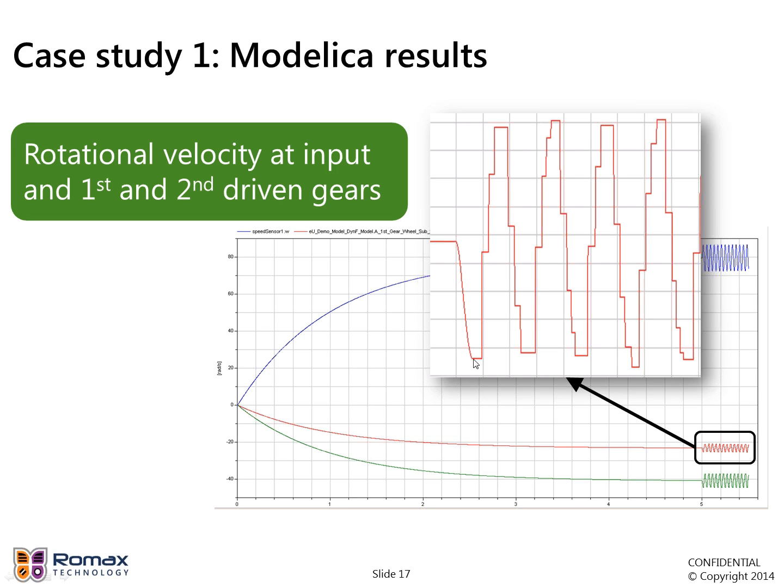At various points here, here, here and here, you can see the velocity is not smooth, it goes constant. And what that indicates when the velocity is constant is that there are no forces acting on that gear at that particular moment, i.e. it's not in contact with the other gear. It's moving about in the backlash region of the gearbox. And every time it leaves contact, you see the velocity becomes constant there.